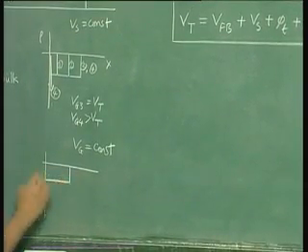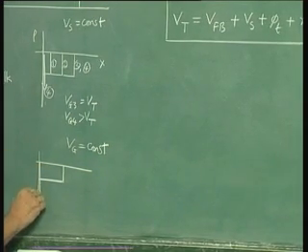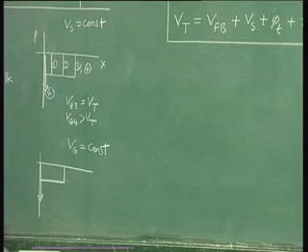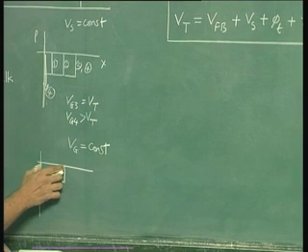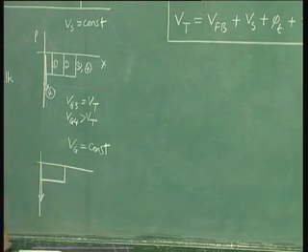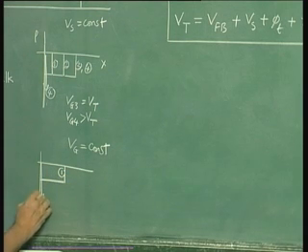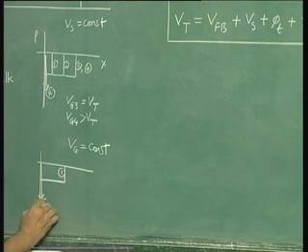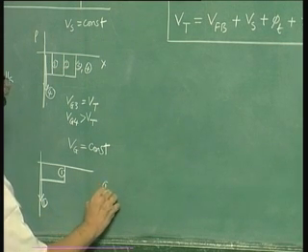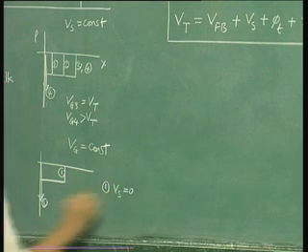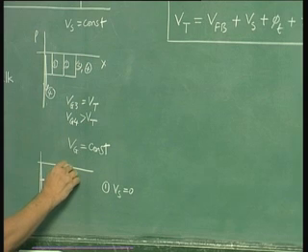Supposing your depletion width was this much, the device was inverted and therefore you had this charge. So this is the depletion width in threshold, beyond threshold in inversion, because this corresponds to Vs equal to 0, and this is also 1. So 1 is Vs equal to 0. Now you are going on increasing your Vs, so what happens is this is expanding.